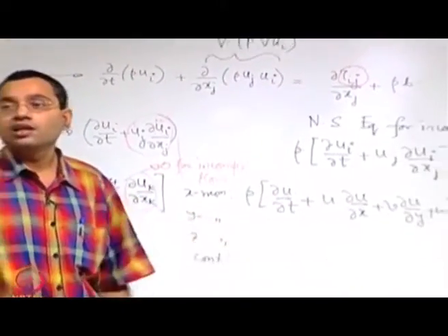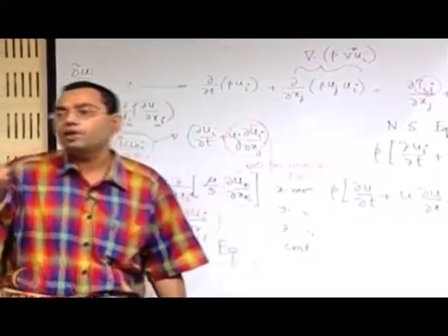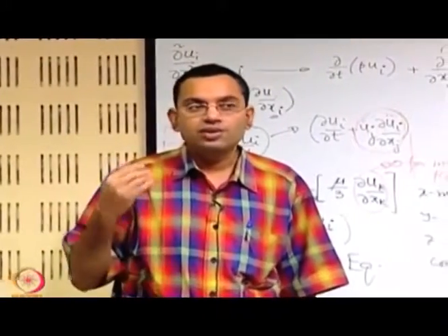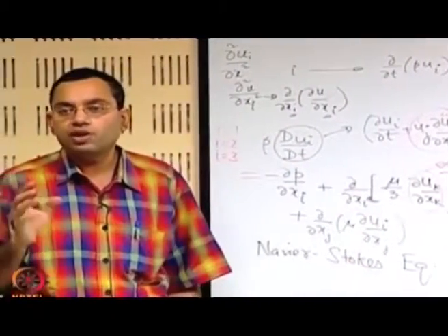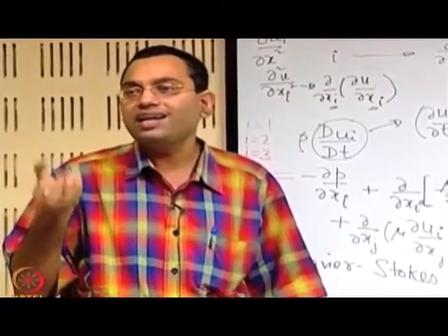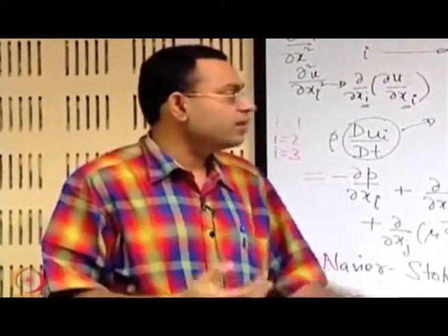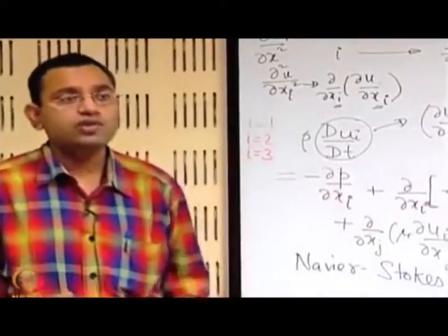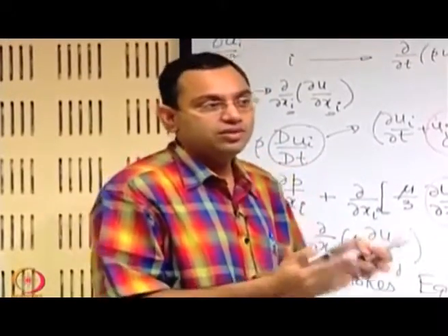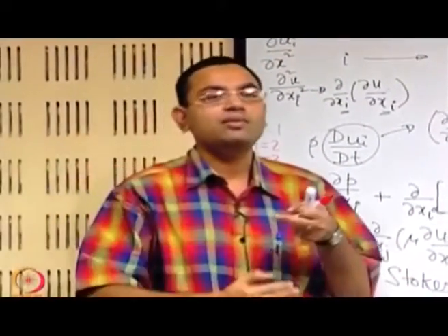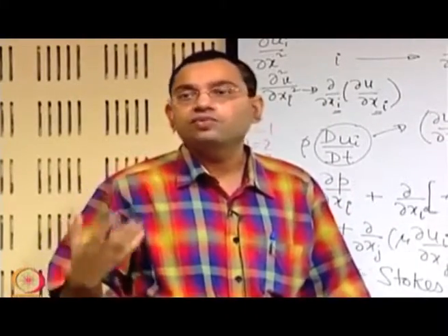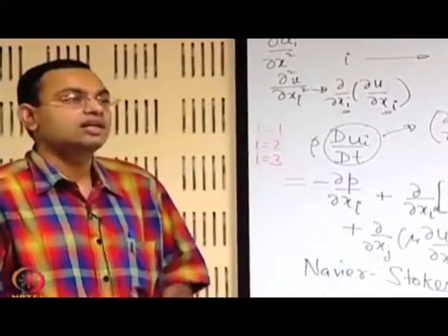because you do not have any term in this equation which is representing a sort of local density or local temperature gradient driven motion or flow, and this is an example which is known as thermophoresis. Sometimes it is called diffusophoresis because of the self diffusion. So these types of motions which are achievable in highly rarefied systems are not manifested in these equations. So what we try to do is to correct the Navier-Stokes equations and incorporate extra terms, so that it may be able to physically incorporate the effects of thermophoresis and diffusophoresis types of motion, and that is how we extended the Navier-Stokes equation.